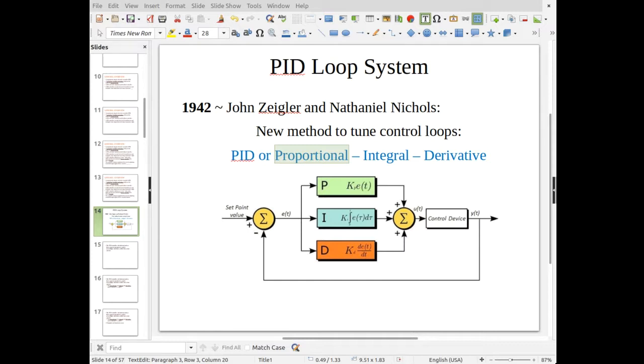The more delay you put in, the slower the system reacts. Because the bigger you make delta t, the slower you are to respond to changes, and then you're reacting to something that didn't happen now but a fraction of a second ago.